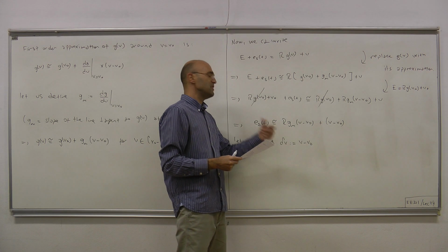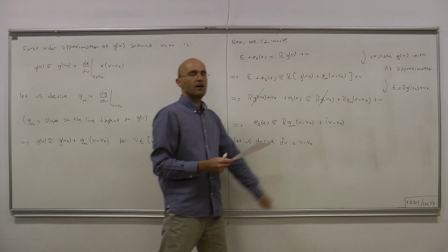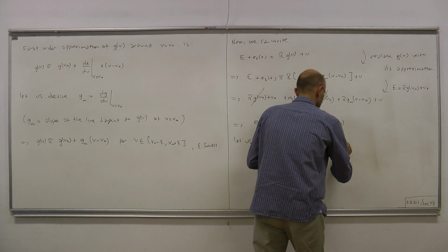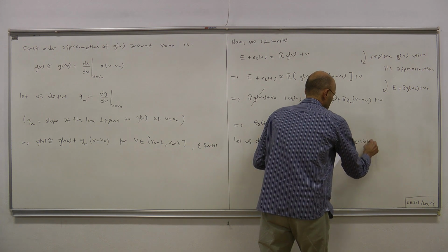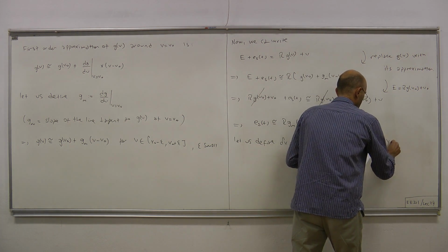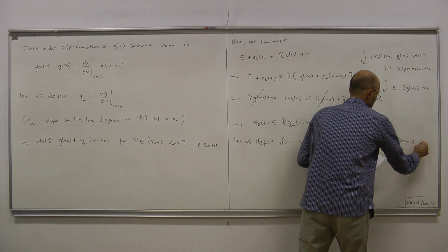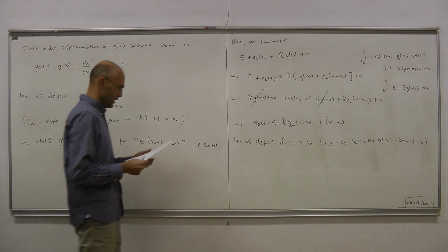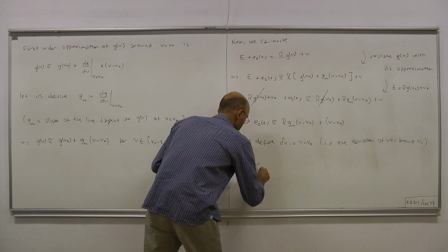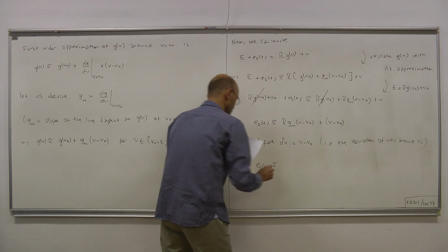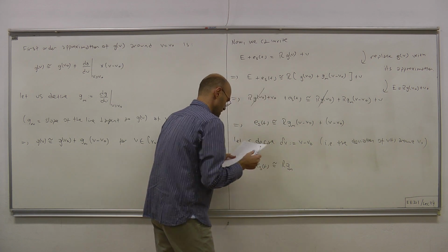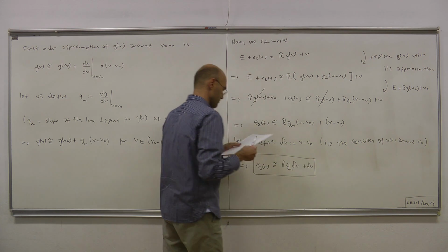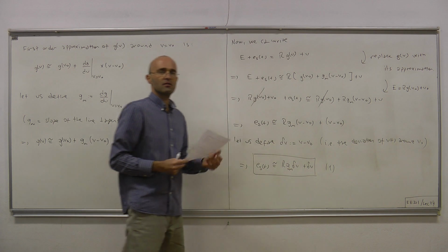This is the deviation of the actual voltage around the DC operating point, i.e. the deviation of V of t around the fixed DC operating voltage. With our new notation, we have Es of t approximately equals R times Gm delta V plus delta V. Let's call this equation 1.